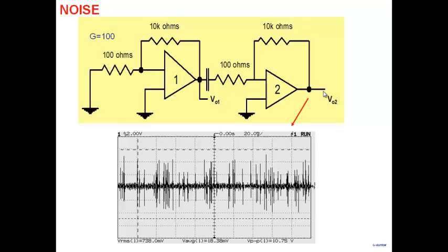How small a signal do you think I can apply? Well, this is the output noise, right? Output noise is 750 millivolt. When you take this 750 millivolt noise and transform it to the input, what kind of an input does it correspond to?